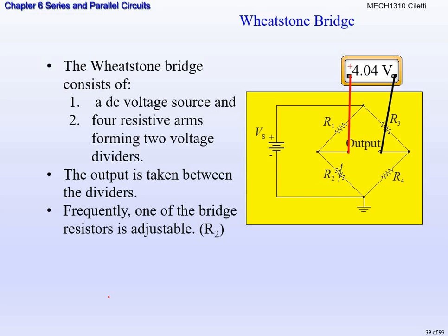We have variable resistors, so R2, sometimes we're going to call that RV for variable. That's the adjustable resistor. So when you're working on your thermostat in your house, that's where, hey, I want to set my indoor to 68 degrees or to 72 degrees. So you're setting a resistor value that's going to adjust it to 68 degrees. Where R1 is going to be the resistor that changes based on temperature. So that resistor, as you go up and down in degrees, that resistance value changes.